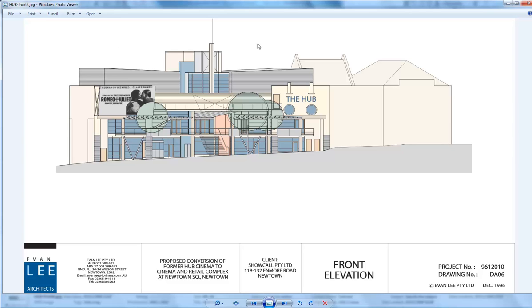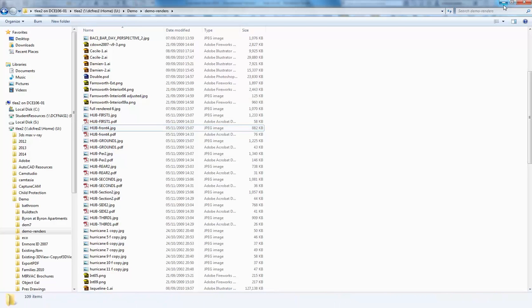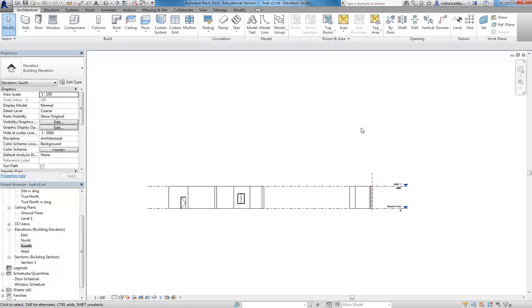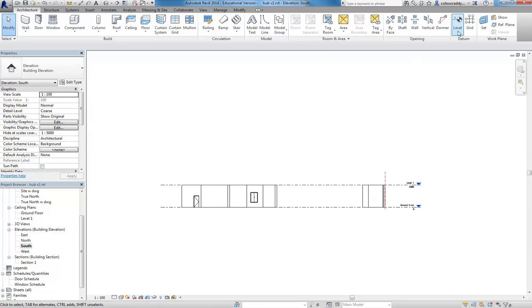So 4 new levels. And that's the way you want to be thinking. You don't need to have all the levels worked out, but you should have a rough idea of the main floor levels you'll need. And then you need to add a roof level. Always you'll need an extra level for the roof. And it's no problem adding levels later, but again, if you can have them in at the beginning while you're setting up your walls and other things, it will help.